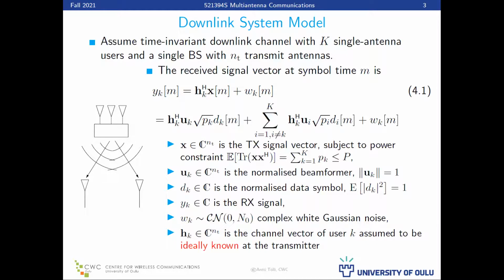So in this slide, we have a time-invariant channel. The channel is fixed, for simplicity. Of course, everything extends, and we can add an index so that the channel keeps changing, and we do the optimization over time as well, but it gets hugely complicated, and you never do that in fact. You don't know the channel in advance. Well, you know the statistics, and you do something, like a water filling type solution. But here, for simplicity, we just assume a fixed channel realization.